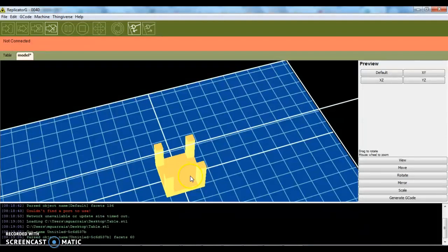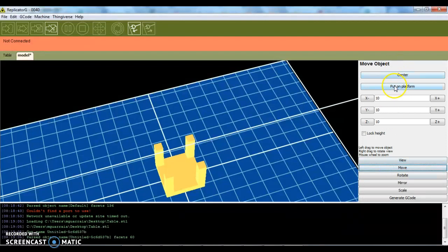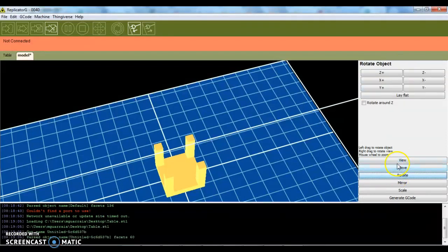And if I had this table right side up, there'd be a lot of hollow space underneath it. It wouldn't print very well. It would build all this support material. It would take forever, and it would do a crappy job. If I had designed it right side up, it's not a problem. I can rotate the object before I print it, and I can move it such that I place it on the platform. You can rotate it a certain amount and all that. So it wouldn't be that hard, but I've 3D printed before, so I knew to do that